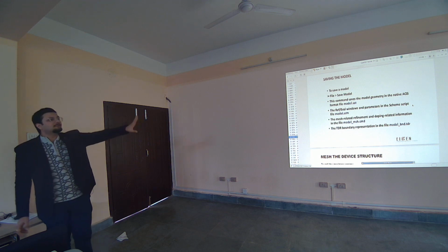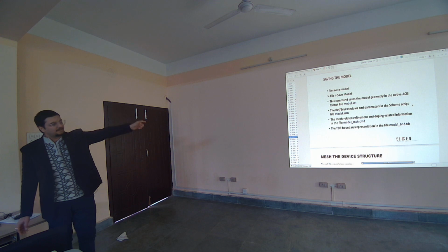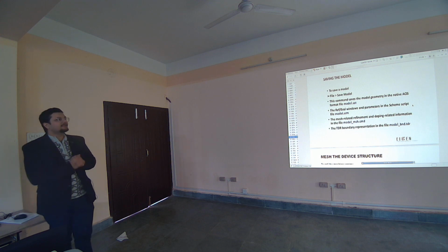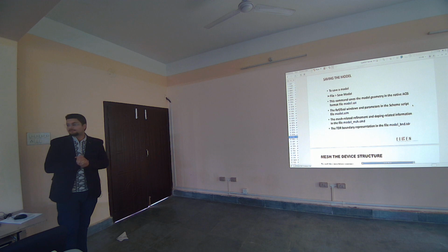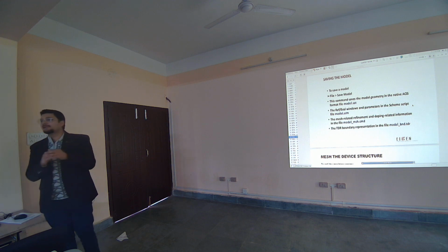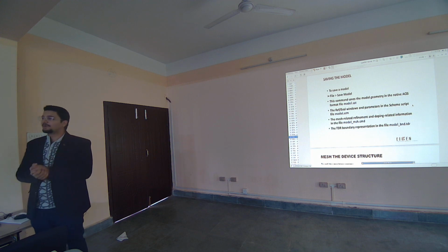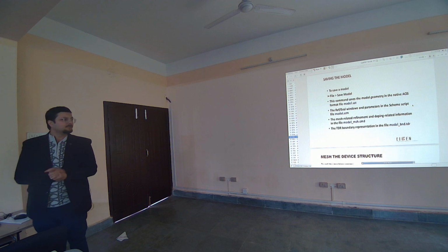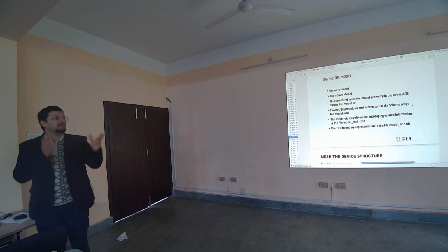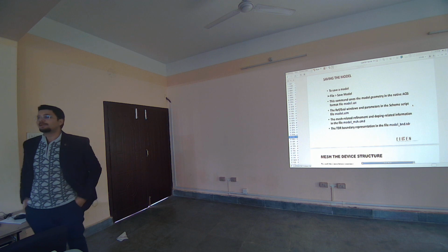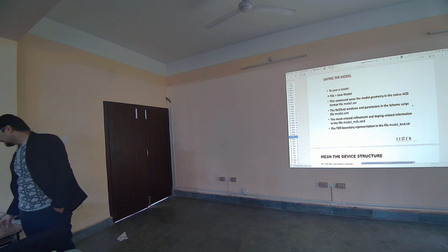Right? So the first file was the file name .set. Then the second file is the scheme language file, right? Whatever we were creating in the GUI manually will get created automatically in code. That's what we call scheme language commands, right? Yeah, scheme language code. The extension for those scheme language codes is .scm. So you'll find the .scm scheme command extension right there.